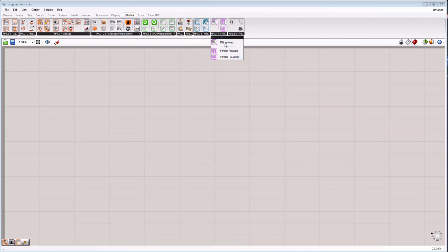This is something for milling. Milling we actually do have, but the milling processes in HAL are pretty bad, so we don't tend to use those. We will use a different software if we wanted to use them. And then finally we have one for grippers. These two little functions here are fairly nice. Pick and place are predefined ways to pick something and place it. And this is a predefined function to give you a stack of material, which we will go into for project 2, but not now.